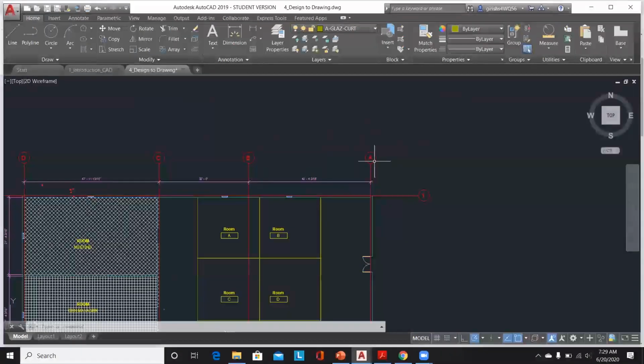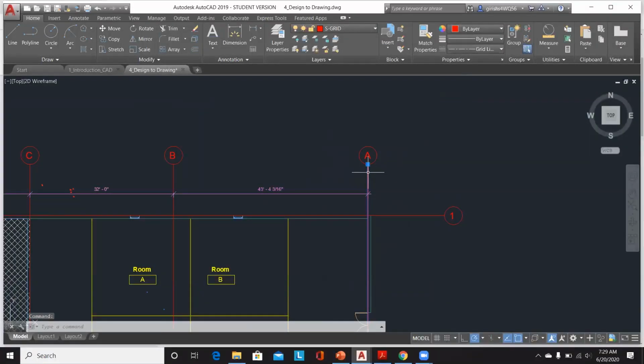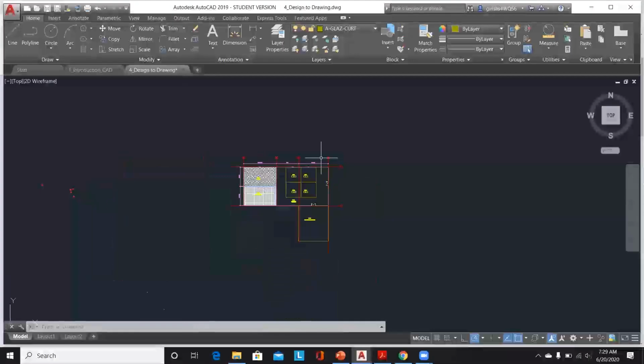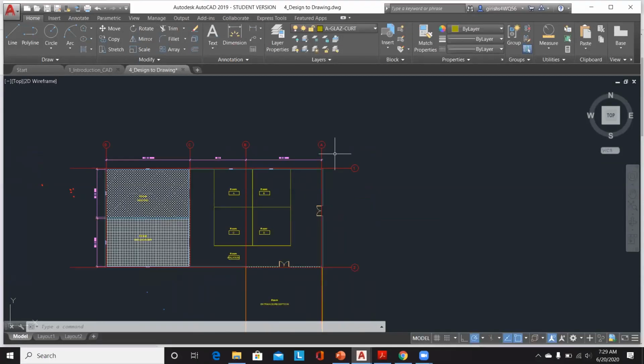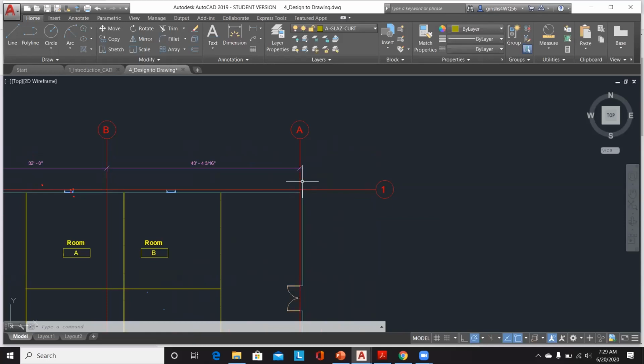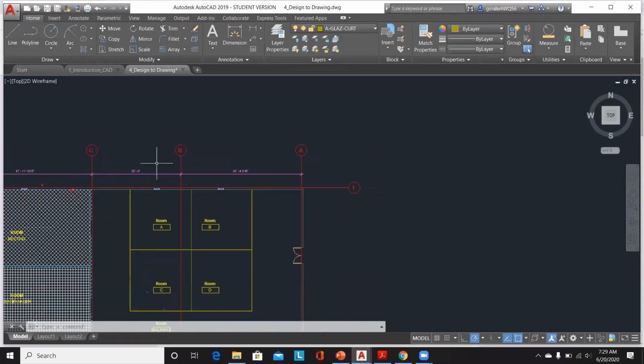The first element that you can pay attention to is adding grids. So why do we add grids? Grids are nothing but a reference element that are required in drawings, with reference to which we add our annotation to model elements too. For example, this is a particular floor plan which I have modeled based on a concept layout, and then I have created a system of grids based on the boundary of wall layers to add annotation between, let's say, two grids or the two wall elements.